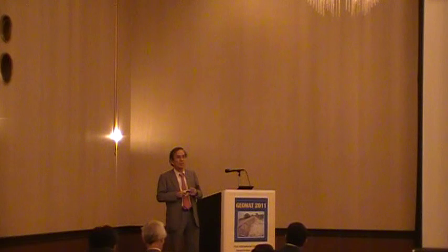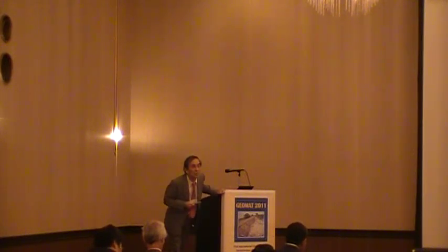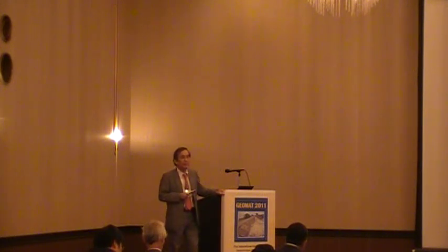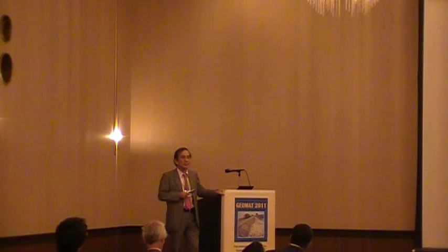Yeah, that's what I wanted to know, because when you fill the river side, you took like 24 hours to fill this side. During that filling, the part of the embankment is getting saturated. So it's not due only to deformation of the unsaturated slope, but it can again consolidate.